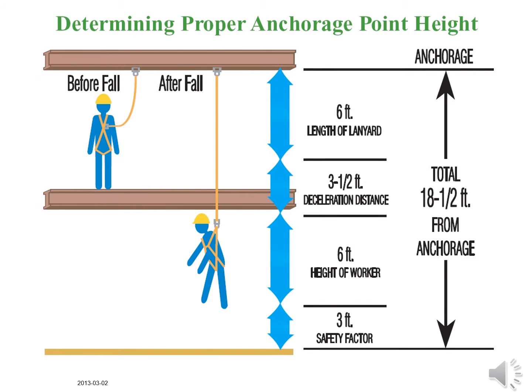Before identifying an anchorage point, the worker needs to calculate the potential fall distance. While the physics involved may get complicated, the math is actually very simple. For example, let's assume that the worker is using a 6-foot shock-absorbing lanyard attached to a full-body harness. According to the lanyard specifications, the maximum elongation of the shock absorber as the worker decelerates is 3.5 feet.